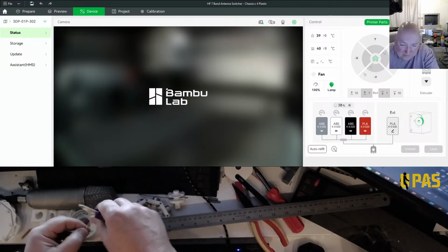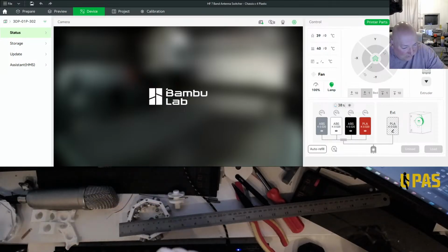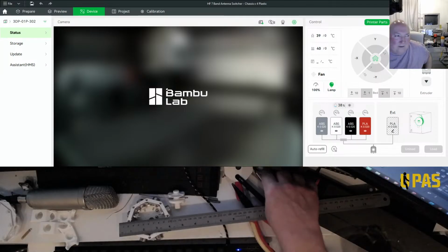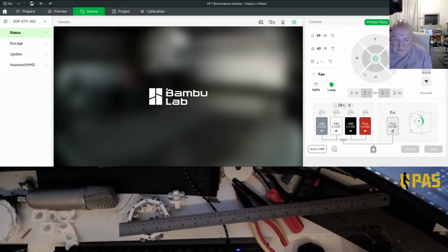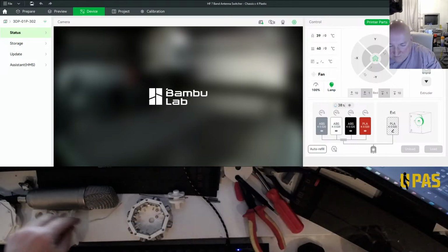So I need another 8 of them after. Whoops, dropped it again. This solder braid I bought was never desoldering braid. It was never any good anyway. You have to dip it in flux. There's like no flux on it. Right, so we've got a spare bit for after.